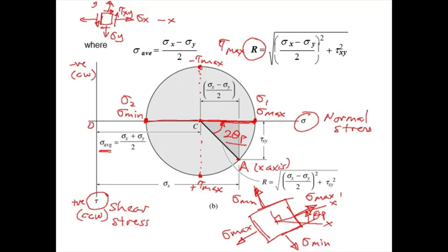Okay, so that is how useful this Mohr circle is, to help us visualize what happens to the stress element and where we can easily find the maximum and minimum stresses acting, right? And you won't make a mistake. So we have sigma max and sigma min. And the other thing you can notice is, at the point where we have sigma max and sigma min, it is on the axis of normal stress. And the axis of normal stress is 0 value for shear stress. So we know that on this axis, both x prime and y prime, where we have max and min normal stresses, we do not have shear stress, right? So that is how we read the Mohr circle.